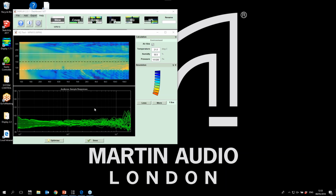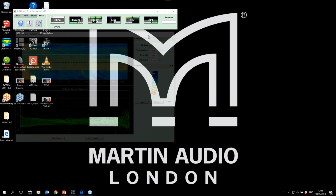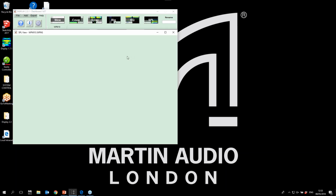Okay, now the optimization is done, we can see the index plot has changed as previously mentioned, with the yellow down to the blue with the highest to the lowest SPL, and we've got a nice consistent frequency response through the slice. We just click done now and we can review that in more detail in the SPL tab.